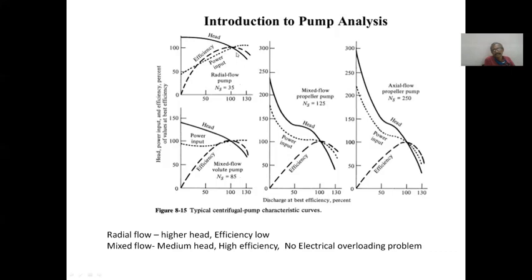When water level is not too deep, your electric winding will get burnt. When water level is at a shallow depth during monsoon, you will find that it will operate at a lower head but higher discharge, and during that time power consumed will be more, and there is possibility that the electrical winding may take more current and it may get burnt.